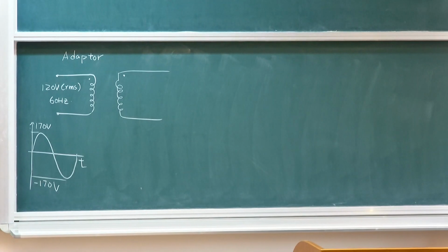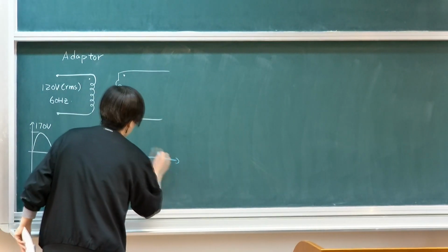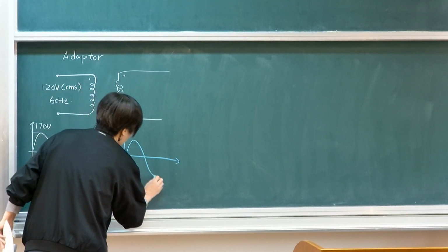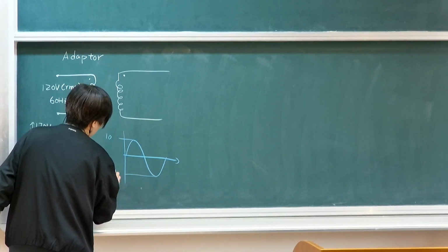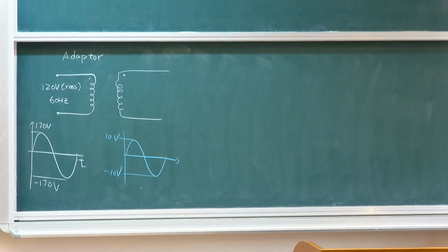So before the rectifying circuit, you move to the next level where you scale down your peak level. Through a transformer, we simply scale down, for example, to minus 10 to 10 volt maybe. If your final target is 3 volt, you don't want to go down to 3 volt at once, because through the process it will take out a little voltage.